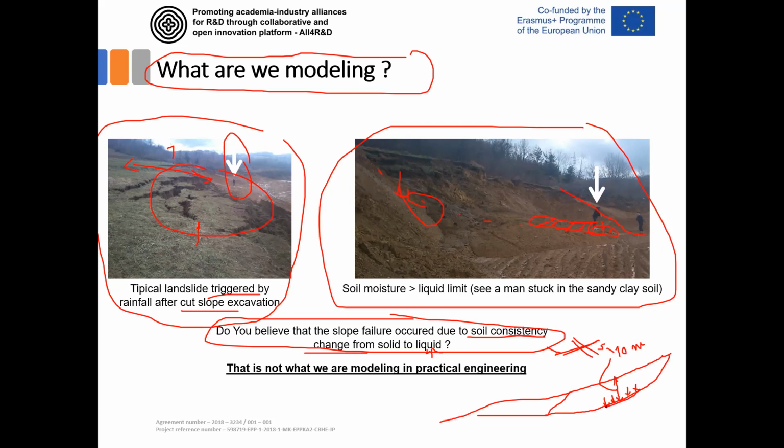When the soil is under this kind of pressure, which is 10 meters multiplied by the unit weight of the soil, about 10 in submerged condition, then you practically have about 100 kilopascals at this level. It's practically not possible for soil to become liquid under such a large surcharge pressure.